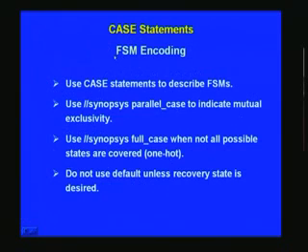Regarding writing an FSM, a state machine, you can use the case statement, of which we have already seen a couple of examples, to describe basic finite state machines. Synopsys parallel case indicates mutual exclusivity, and full case is used when not all possible states are covered, as for instance in a one hot machine. And don't use default unless you want a recovery state. In one of the examples we considered earlier, we used that recovery state as the default, so we took it to a safe initial state S0 while looking at an FSM earlier.